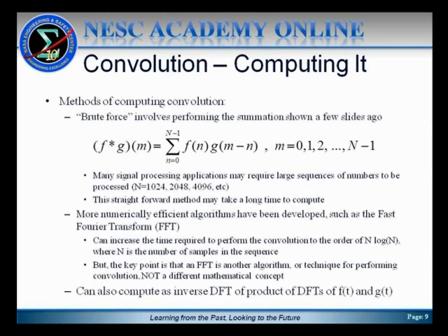Why those specific numbers? Those happen to be powers of 2. And it's very important in signal processing that n, the number of samples of a signal that you sample to perform the Fourier transforms, for the discrete Fourier transform should be a power of 2. So 32, 64, 128, 256, 512 samples, etc.